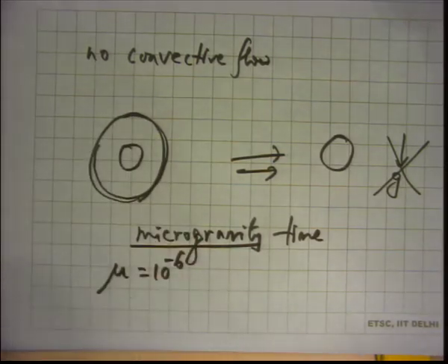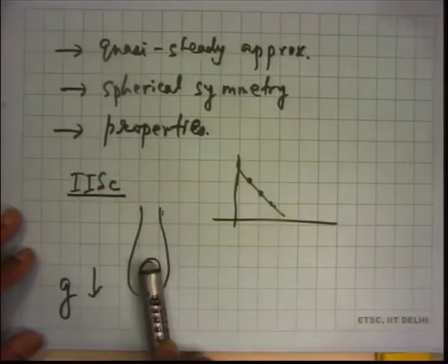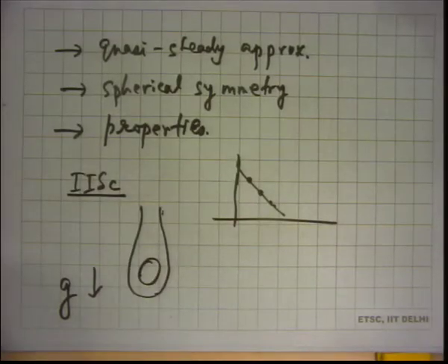The one which I had shown you in the last class was in fact not on a space shuttle, but in a free fall experiment. So you could actually see a spherically symmetric flame. But in general, that will not be there. In general, you will have a flame which looks more like this, but there also you can write a d square law, and the d square law is d squared equal to d naught squared minus k into t, and that turned out to be linear. You saw that red dot moving, it was actually generating a straight line.